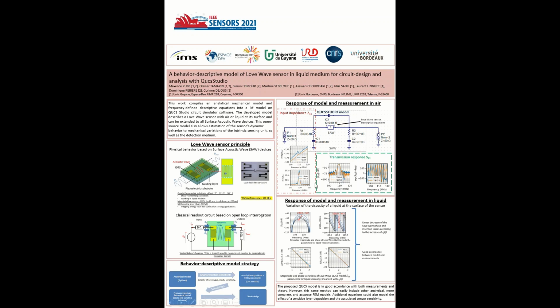Then we try to also take into account here the behavior of the model in a liquid medium for an increase of the viscosity of a liquid at the surface of the device. You can observe that both model and the measurement are in good accordance for the change in the magnitude and phase of the transmission parameter S21.